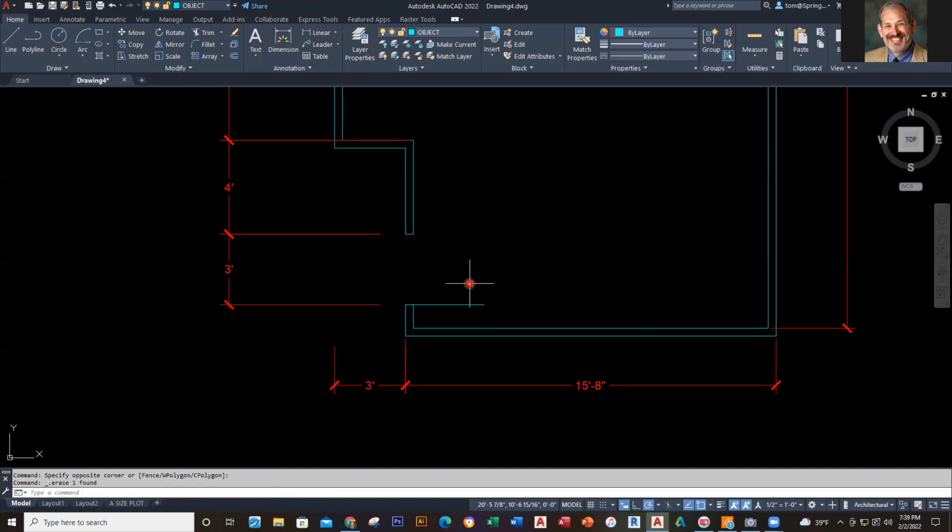I could also do start, center, end the opposite direction. Let me try that one. That might make it a little bit easier. So I'll go start, and then center, and then my endpoint, I want to go there. So I hold my control key down, I can go there. That's one way to do it. So I can knock it out there by holding the control key down.